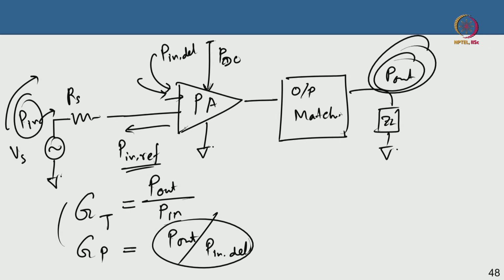One thing that we did not talk about here is that you are bringing the input power at a certain frequency f0, which is called the fundamental frequency, and you want to deliver power at the same frequency f0, but you are going to get some harmonics, at 2f0, 3f0 and so on.